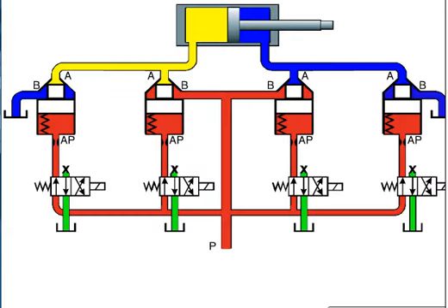By using 4 slip-in cartridge valves with a directional control on each to operate a cylinder, you will get 12 flow path combinations. Because you can use individual slip-in cartridge valves for each flow path, you can select sizes that are appropriate for the amount of flow.